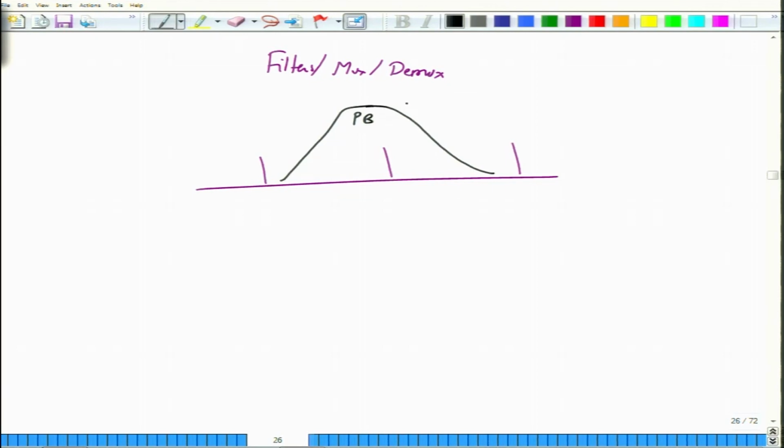One would expect the filter to have an ideal pass band and then cut off abruptly, but in practice you know that this brick wall characteristic just cannot happen. So what you have is one device in this way, and then there is a pass band here again, and there are these skirts as we would call them. These are called the pass band skirts, and there will be some amount of crosstalk. When the spectrum occupies this region, there is a crosstalk between the two adjacent channels.